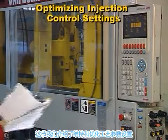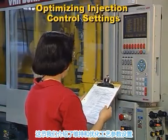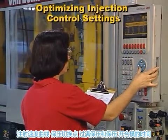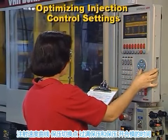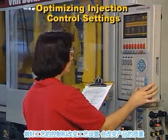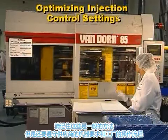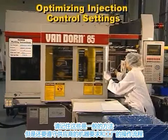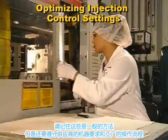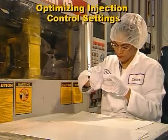In this lesson, we've described rules and procedures for setting and maintaining the injection control settings, fill rate profiles, transfer set points, packing and holding controls, and mold open and close timers. Making control adjustments and changing processing conditions will have an effect on molded part properties. But remember, these are general procedures, and in all cases you must follow the specific operating procedures for your molding process as published by the equipment manufacturers and as given to you by your own plant management.